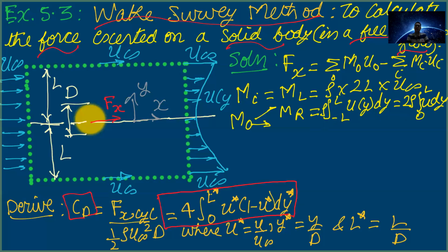Now, as I mentioned earlier, we need to realize, which is very important for this problem, that although you are given velocity profiles only at the inlet and outlet, at the outlet the mass flow rate is less than the inlet mass flow rate. So you also need to realize, which is hidden in this problem, that there is another outlet, which I am calling the side outlet, corresponding to the top and bottom wall.